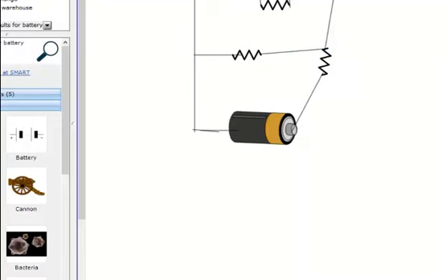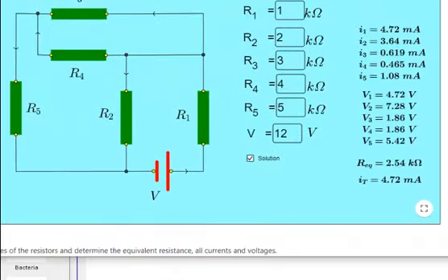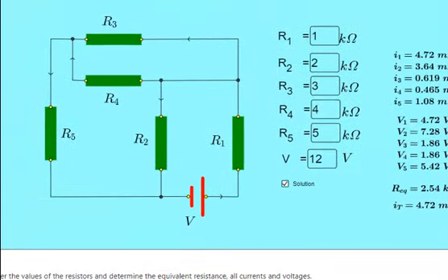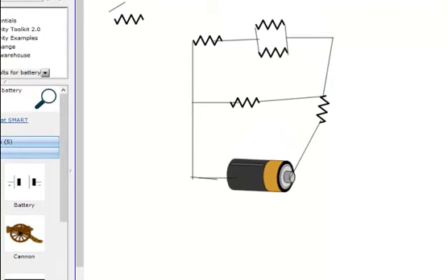Now that circuit diagram is actually the same as this one. The result should be 2.54 ohms or kilo ohms. And this one here I claim is the same one, but this is the way you would find it actually in a physics book. I just noticed it was a little bit off screen, wasn't it? So these two are in parallel with each other, in series with this one. Then all of this here is in parallel with that. And then all of it is in series with this one.